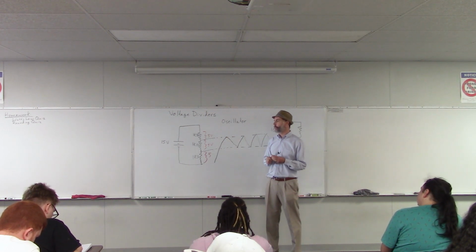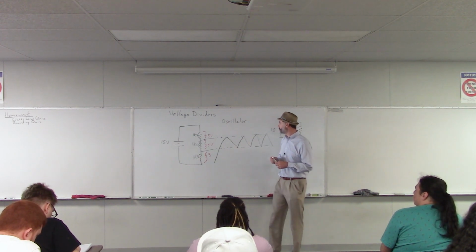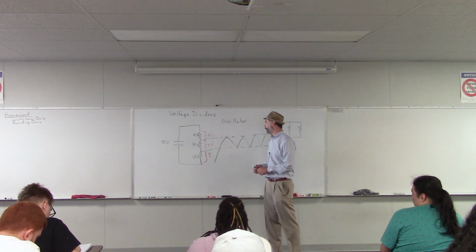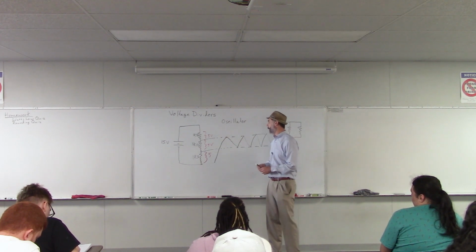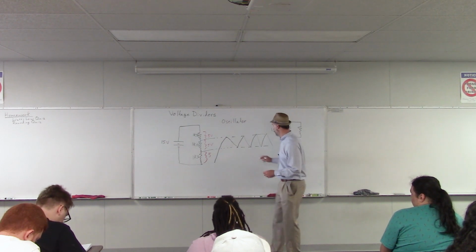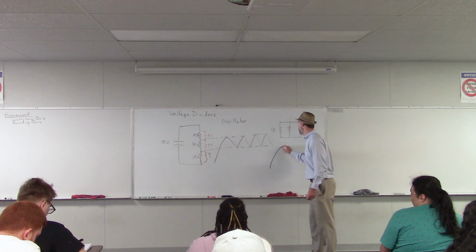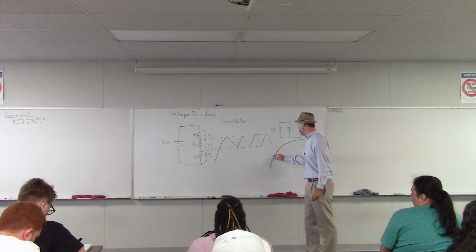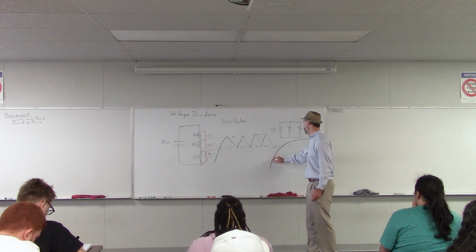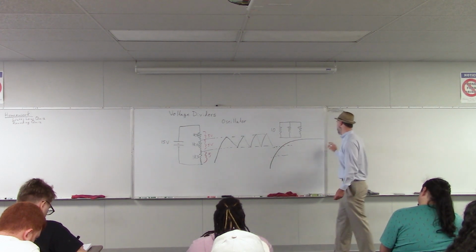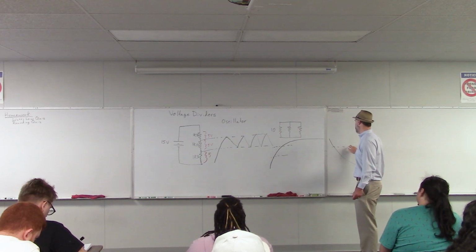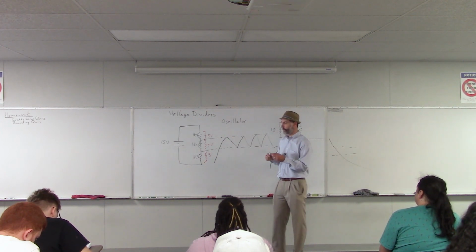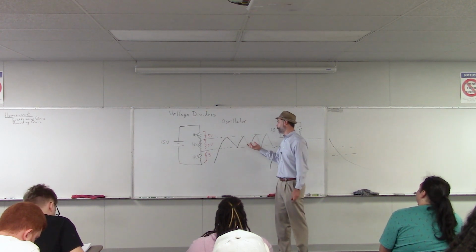What determines the shape of the waveform for the oscillator? The basic waveform inside the oscillator is determined by the charging of a capacitor. If you looked at the whole wave, it would kind of look like this, and it would charge up until it got to some final value. But what we're seeing is just this little part right in the middle, where it's charging up. And if it discharged, it would look like that. That's what determines the shape inside the oscillator chip, or the oscillator circuit.